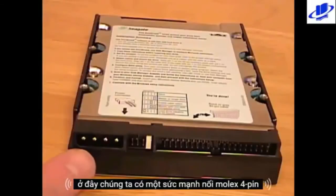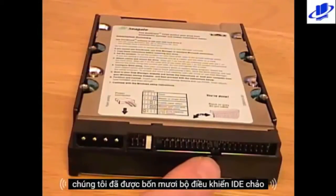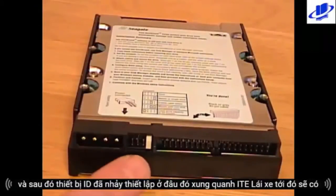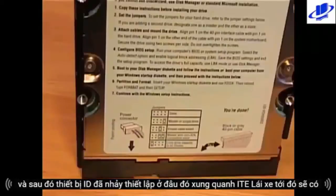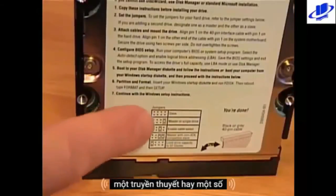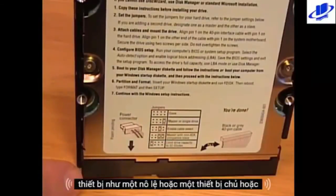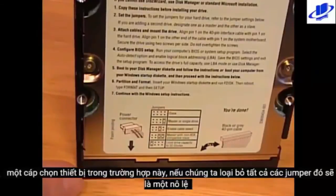Here we have the 4-pin Molex power connector. We have our 40-pin IDE controller connector. It has a keyed notch here so our data cable can only fit in one direction. And then our IDE device has jumper settings. Somewhere on the IDE drive there will be a legend or some indicators to indicate which jumper setting will specify the device as a slave or a master device or a cable select device.